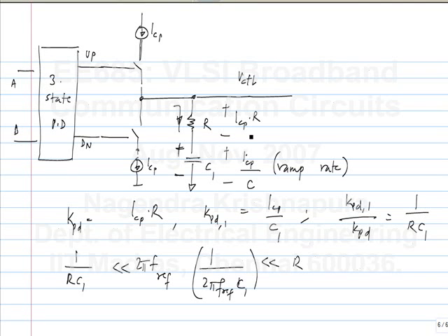So this is quite simple. You can make this integrator plus proportional combination using op amps and so on. For instance, you can pass currents through a circuit like this, or you can have more complicated circuits which do the same thing. Using an op amp, you can make an integrator and you can make a summing amplifier. So you can make any of these combinations with different constants.